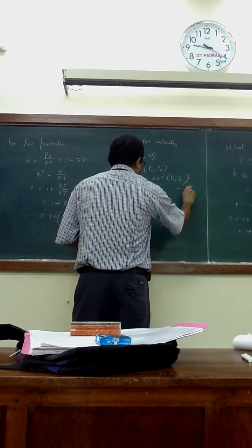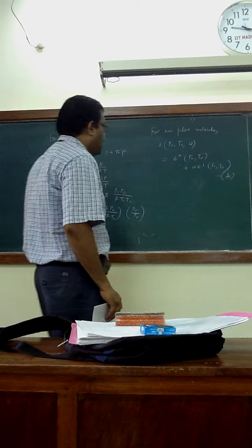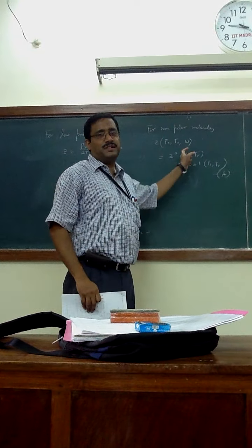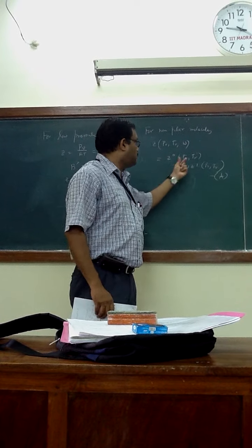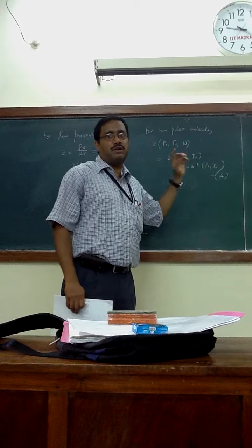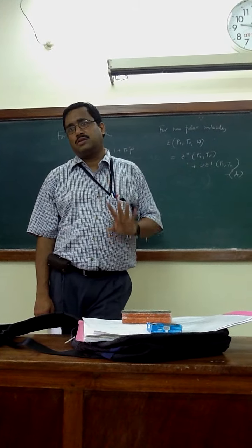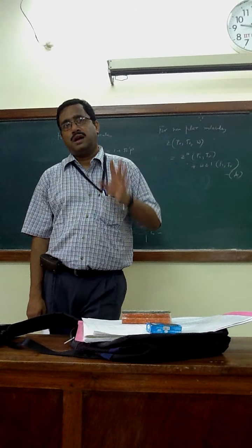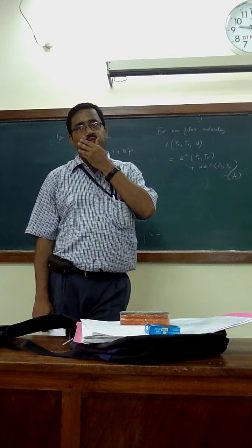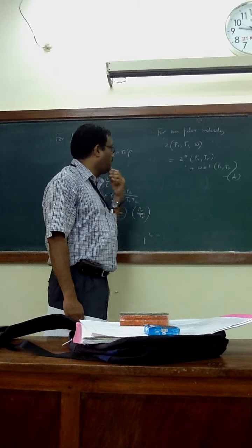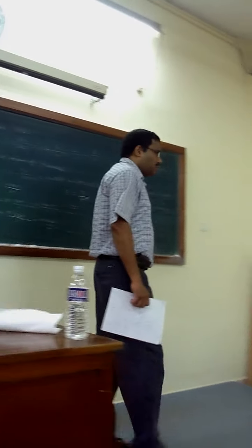Equation number 8. So you can have some kind of linear relationship if you include this Pitzer acentric factor. Van der Waals equation of state is the only equation of state where W has no role. Otherwise SRK, PR have a role. RK doesn't have a role, but RK has some other nonlinearity. So if we have other second class equations of state, that role has to be counted.